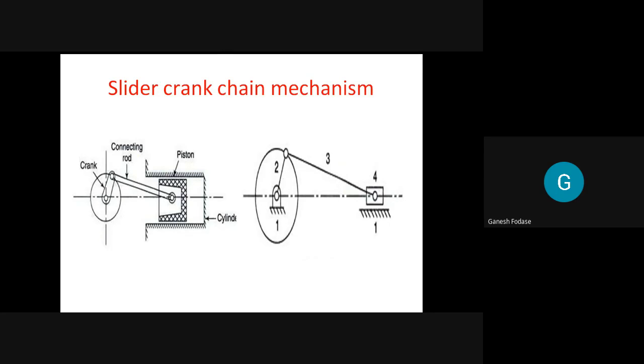I'll give more clarity on the concept of mechanism and machine. As someone said, clock. But what we can say about the clock in this case is that the force or energy provided is not more than what is required to overcome the friction of the parts, and that is utilized just to get the desired motion of the mechanism and not to obtain useful work. So in that case, it is just transferring motion, not work, and hence we can call it a mechanism.